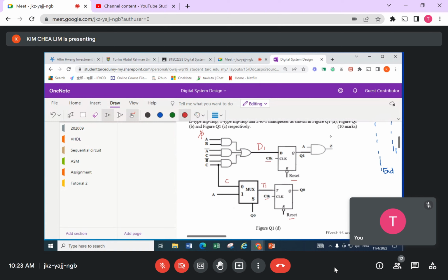Maybe I put down here, this is the output set. The two outputs, Q1, Q0 from the flip-flops here, are actually not the output for the circuit, but are going to be connected back to the earlier part. Q1 forms my output, and Q0 connects back to here. All right, so I simply created these circuits here. What is the feature? I also don't know. Just mainly for exam purpose. Okay, question 1 done.